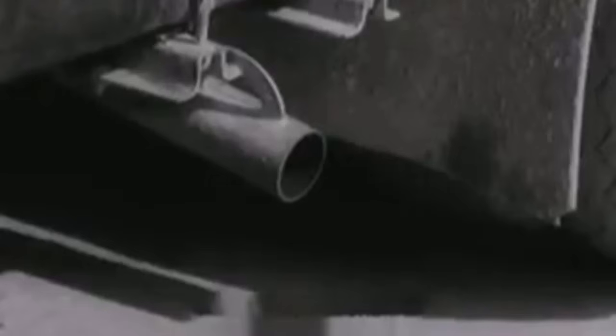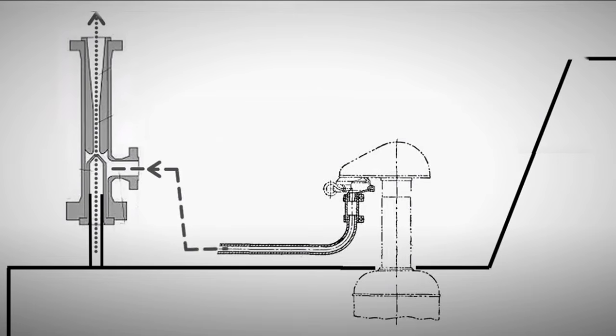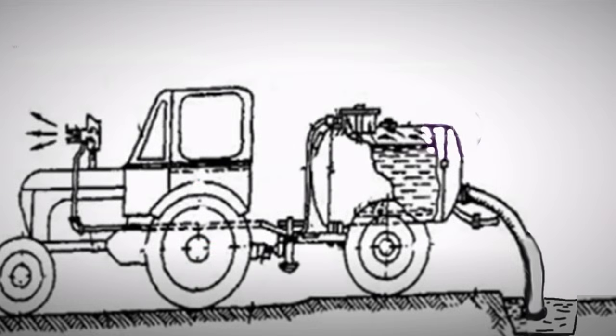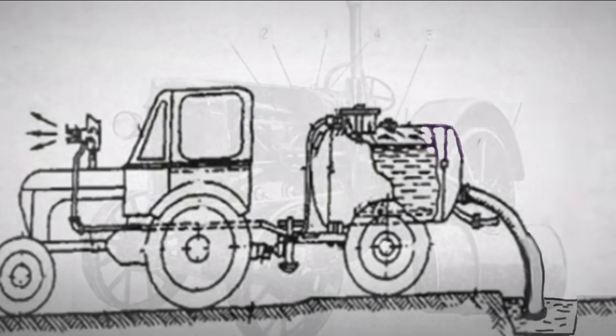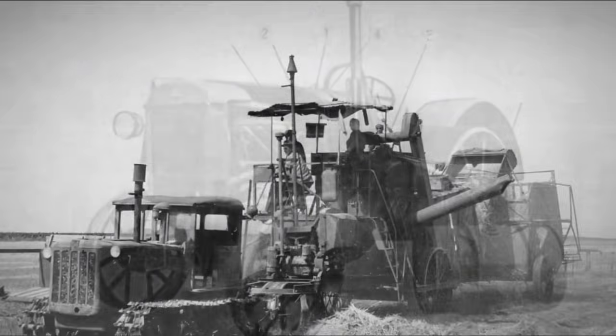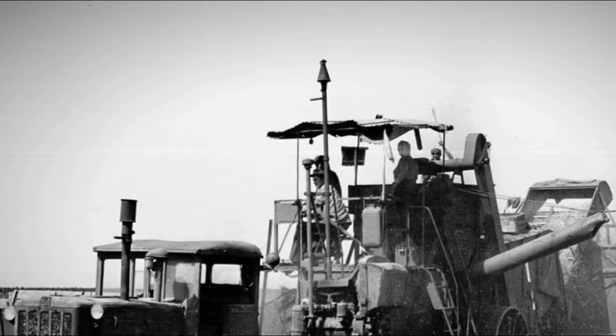The energy from the engine's exhaust gases is sometimes harnessed to perform additional work. For example, using an ejector, the exhaust energy can be used to suck dust from the engine's air filter or to provide engine cooling. An ejector can also be used to draw liquid into tractor-trailer tanks and then discharge it, also using the exhaust gas. This same principle was used in automatic refueling systems for tractors and is used in pneumatic seeders. Some tractors and combines used exhaust-powered horns.